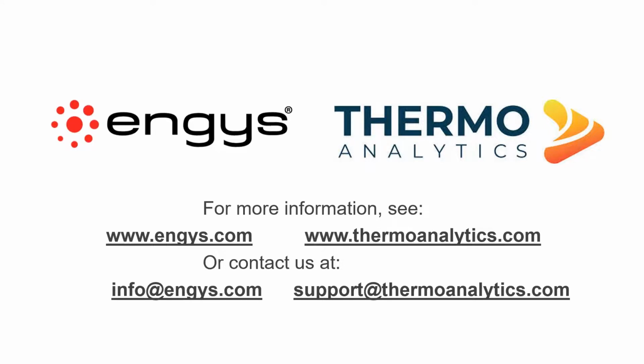How does HELYX calculate the HTC and T fluid? What distance from the wall? We have some applications and function objects to do this, and there are two options. You can specify a bulk temperature as input parameter and use this to evaluate the heat transfer coefficient, or otherwise you can leave the software taking care of getting the near wall temperature at the first cell.